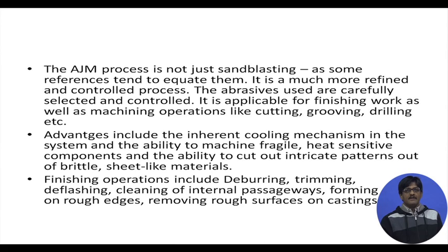The air jet which is coming out has an automatic cooling mechanism incorporated in the process, and it is also able to machine fragile, heat sensitive components and cut out intricate patterns on brittle sheet-like materials, which is not possible by other beams.